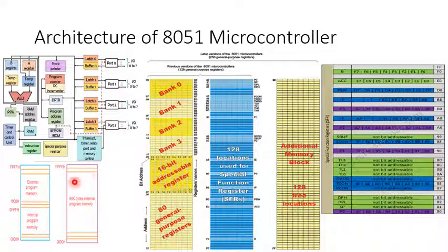Let us discuss the internal RAM and ROM of 8051. Internal RAM has 128 bytes. The 8051 hardware internal RAM is organized into three distinct areas: 32-byte working registers from address 00H to 1FH, and 16-byte bit addressable area occupying RAM byte address 20H to 2FH. Altogether, 128 addressable bits are there.